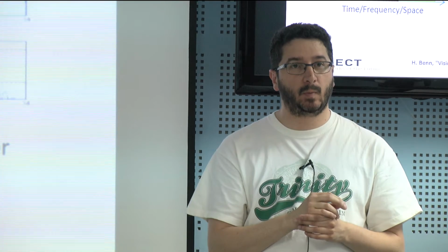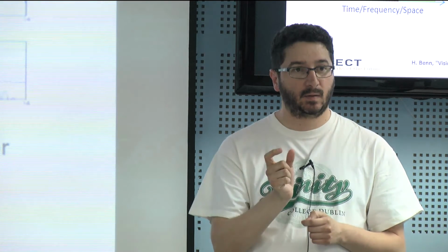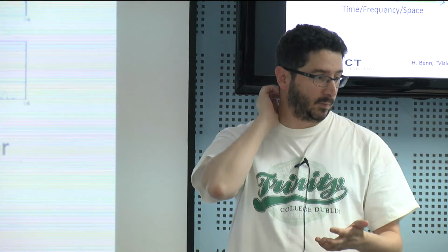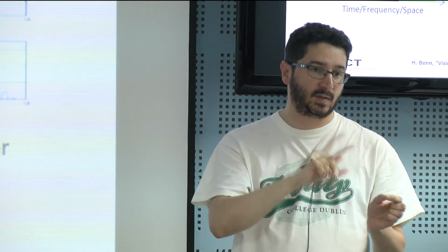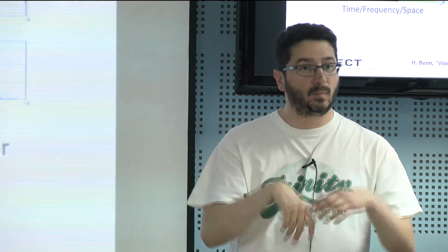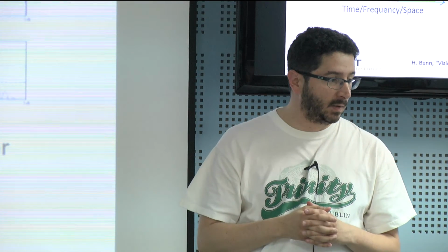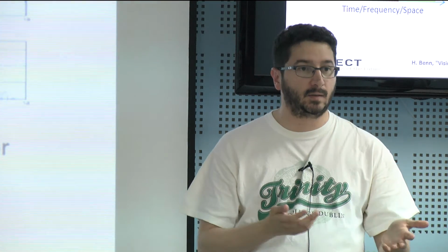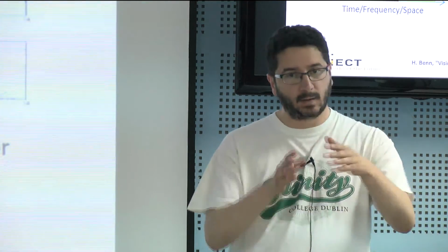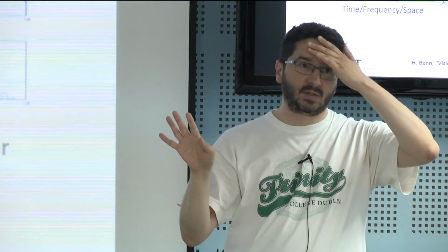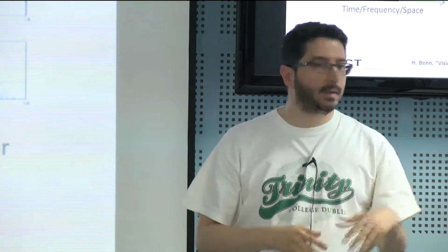Another problem, I think, is the burstiness, right? You transmit now and then, and there is machinery in place with OFDM that requires a lot of exchange of communication at the beginning of a frame to synchronize, right? And if you just transmit very little, it's not worth it. So better to have a sloppier system, if you want, with non-orthogonal subcarriers like filter bank or GFDM, where things are quicker to set up. But then you have the batch processing in GFDM, and the ramp up and ramp down in filter bank, so it's not for free. You do have delay and latency issues there too. The truth is, it's a very rich research space. There's a lot of work going on.